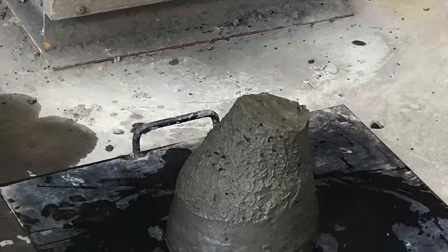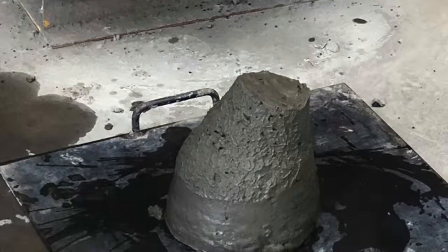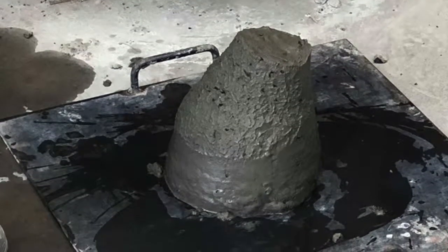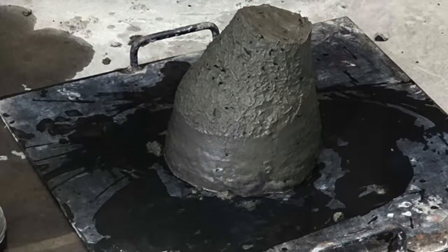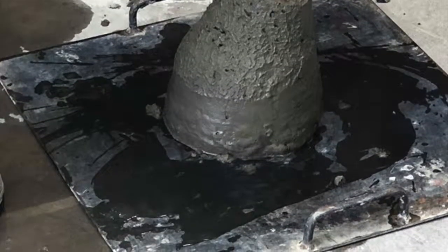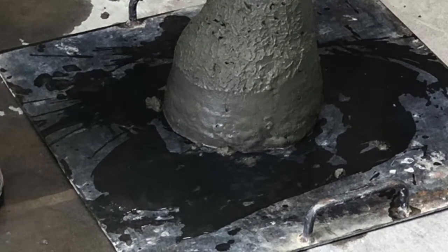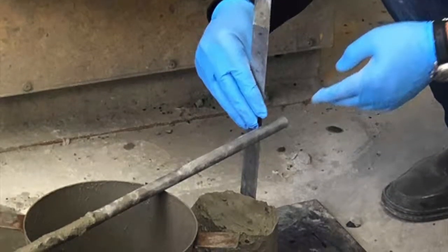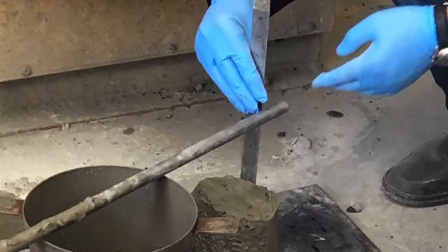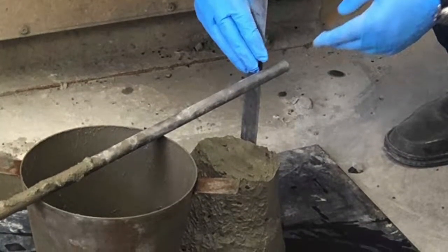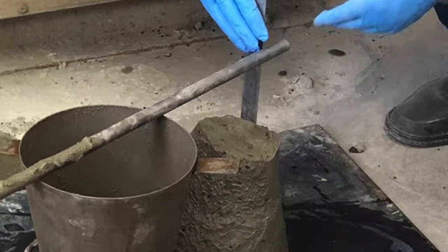When designing concrete, it is important that you achieve the correct ratio of water to cement, sand and aggregate, as if an incorrect ratio is mixed, then it can result in a failure if the mix is watered down too much or there is not enough. This is why it is important that the slump test takes place, as the slump test is a means of assessing the consistency of fresh concrete. All these tests are carried out under Australian Standard 1379.